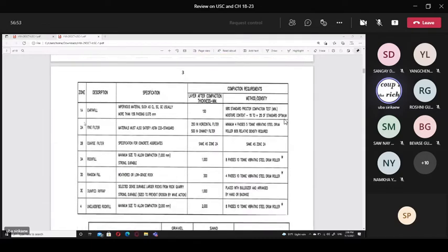So, you see, for the earth fill, what kind of material do they use, by soil classification? CL, SC, GC. They use this material, and it is the specification. You have to compact by the standard method of compaction with moisture content +2 to -1 of optimum moisture content. This is for example. And when you use a fine filter or quartz filter, what kind of material is used?